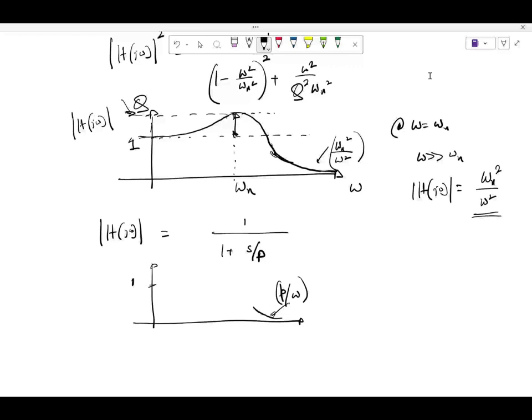So at very high frequency, clearly it doesn't match. The second order transfer function approximated to first order doesn't match. That should be expected because at high frequency, I would expect the higher order terms to dominate. And in a first order approximation, I do not have any higher order terms. So in a high frequency scenario, the first order approximation is going to break.